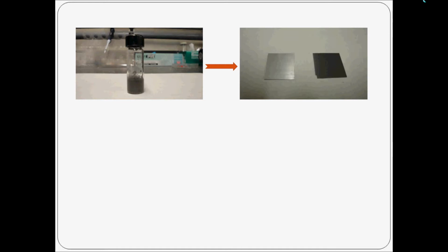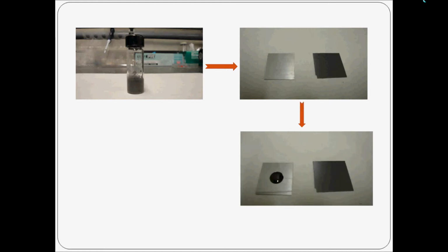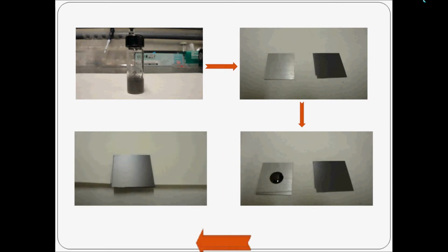The next step is to place the liquid TIM onto the silicon wafer to make a sandwich TIM. So you can consider the two silicon wafers to be the heat sink and the chip. In between there is our nano TIM.